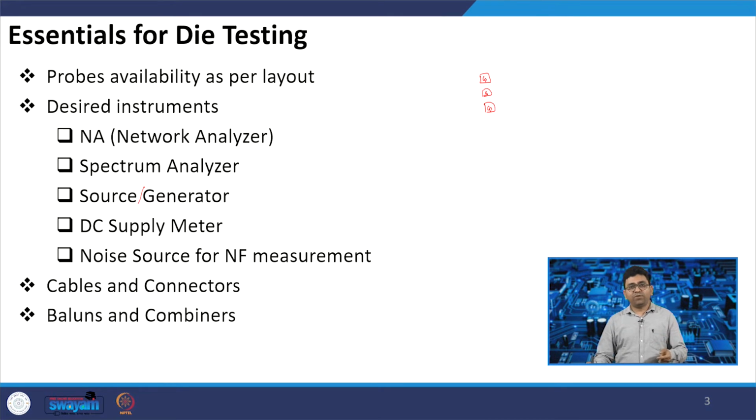You also require the baluns and combiners. If you have a differential signal, you need a balun, or if you want to combine two differential signals, you need a combiner. So, that also is required externally.